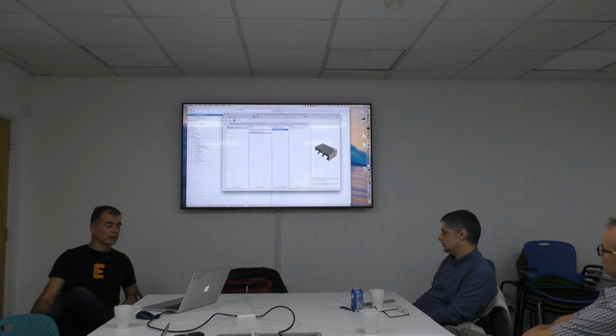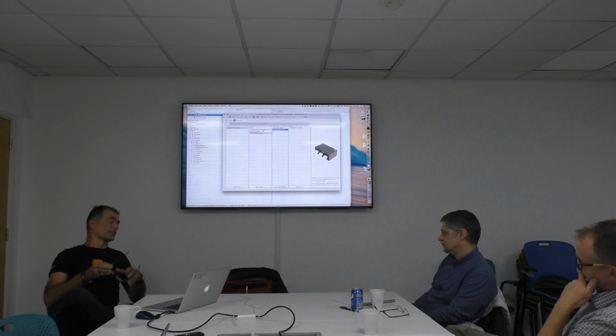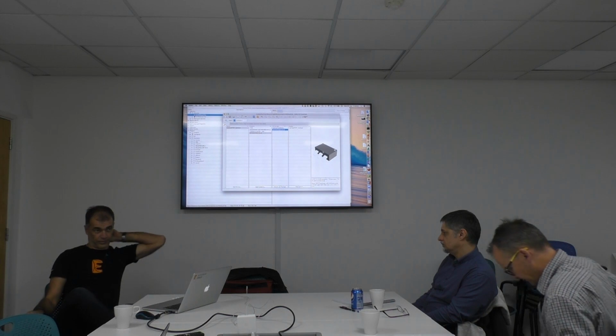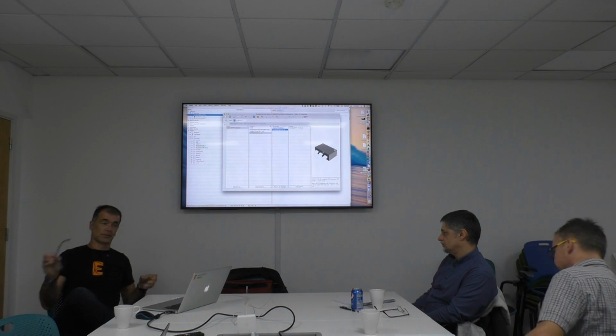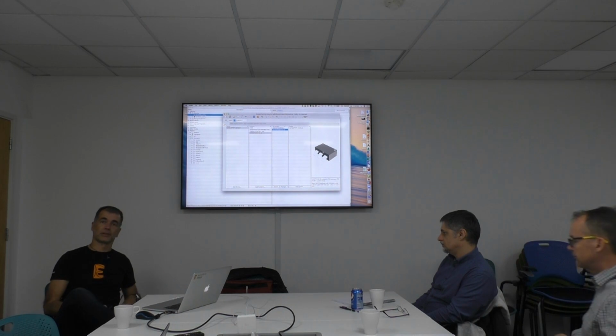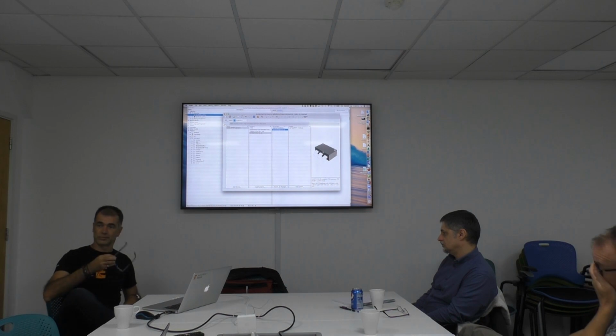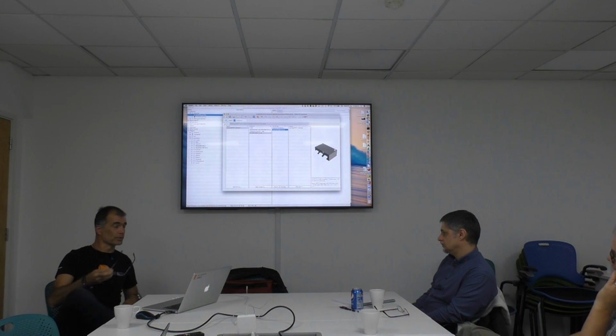We have the footprint generator, that's something new. It will always be limited, and it's pretty limited at the moment, because you have to support different kinds of components, whether it's a BGA, a component, SOP, FPGA or PLCC, whatever. So we have all different kinds, and we are implementing more and more there, so it's more convenient for you.